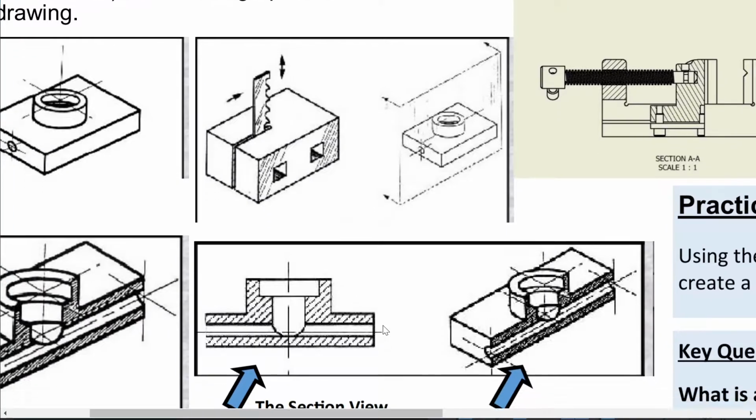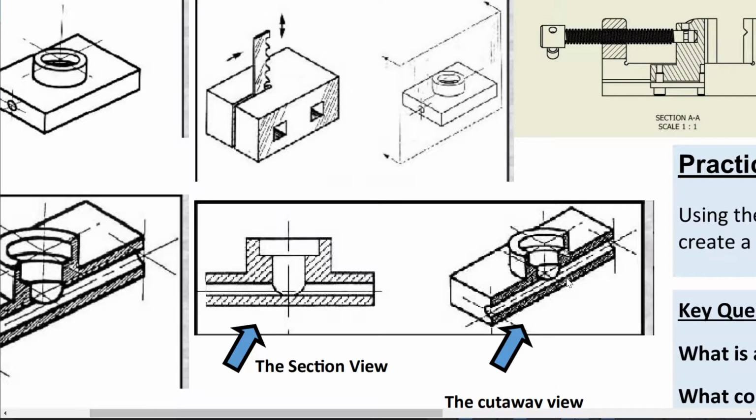they want to differentiate between a section view and a cutaway view. A cutaway view is when we have something that's like isometric drawings. We'll always use orthogonal drawings that are sectioned. And so here we can see that this material here is solid and the rest of this is hollow. So that makes sense when we look at the cutaway view. Okay.